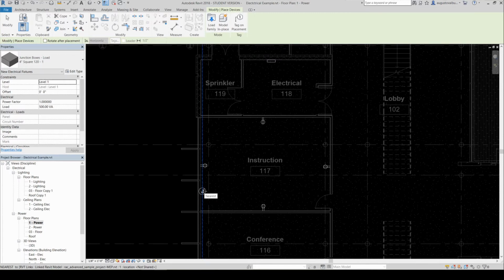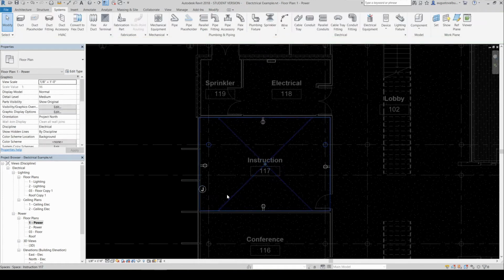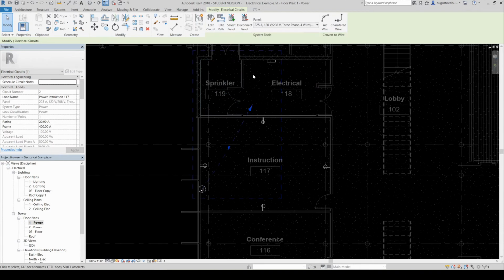We can symbol the connection for, and we can place a note later. But now we have the load. The important thing with this load is something generic that you can tell Revit, hey, I want to assign a load for this, and I want to assign what is going to be the type of my load. How to connect this to the panel? Very simply. You go to the power option, just like you did with the receptacles, and you assign the panel.